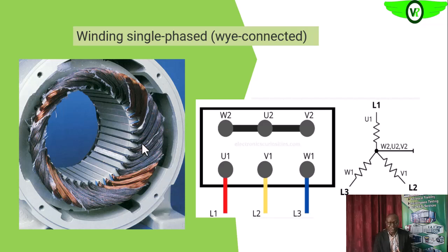So that means that we also need to check to see that our contactors are operating normally, the 3 poles are closing at the same time, even your breakers. Okay, so you can check the description below for the inspection and testing of switches, contactors, and breakers.